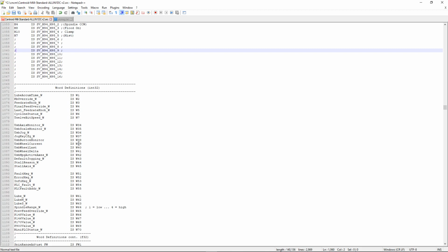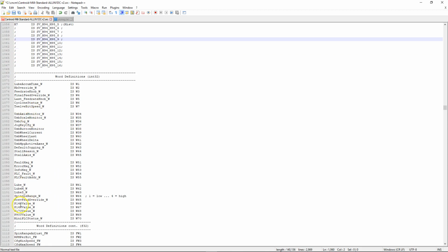Well, once you have that parameter value, you need to figure out what value is in there. So you could actually have a word value associated to that parameter, sort of like these down here. It says P148 value underscore W. This right here is looking at the value of parameter 148. So then that word value would just basically be whatever value is stored in that parameter, and then the PLC program can do some math on that to figure everything else out. We will also go over that, because we will create something later on that will actually use a parameter-based value specifically for a timer. Okay.